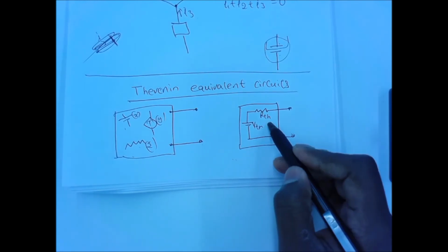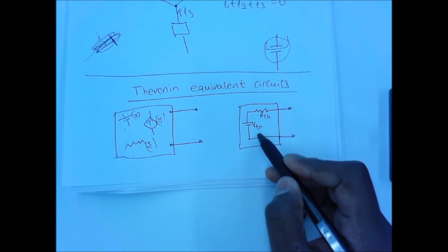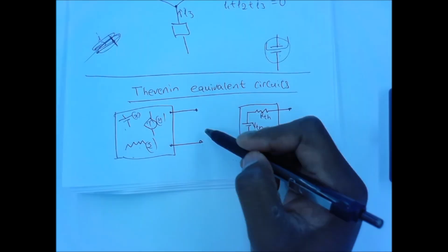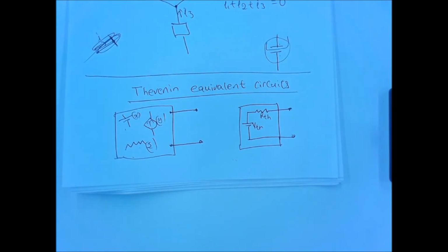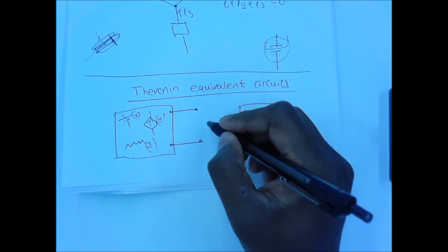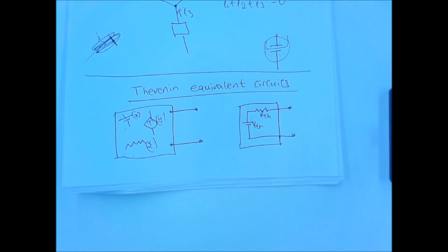How do you figure out what V Thevenin is? Measure the voltage at the terminals. That's it. Don't connect anything between these two terminals. Measure the voltage, and that's V Thevenin. Now, whatever you connect here, let's say you connect some resistance, the current going through that resistor will be exactly the same as the current going through the resistor if you connect the same resistor here.